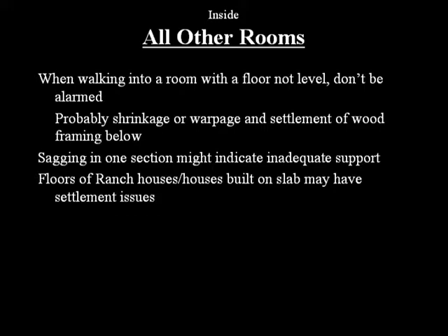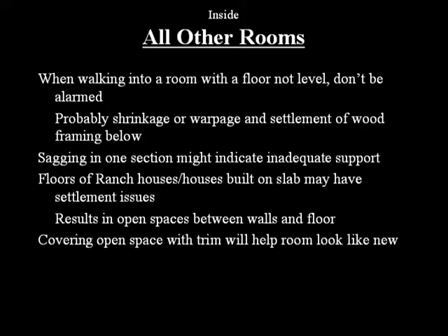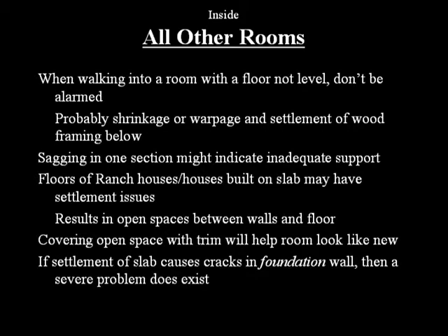Floors of ranch houses or houses built on slab may have settlement issues, resulting in open spaces between the walls and floor. By covering this open space with trim, the room will look like new. If settlement of the slab causes cracks in the foundation wall, then a severe problem does exist and needs to be evaluated by a structural engineer.